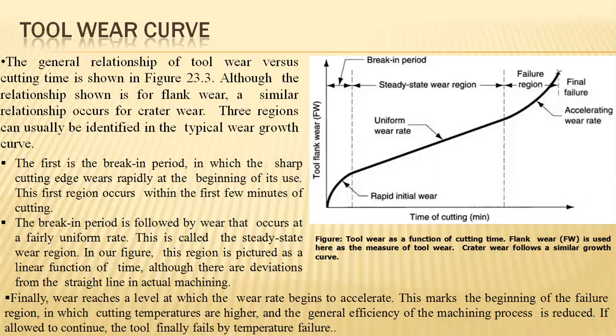Nominally, in the display, it is clearly specified that firstly the break-in period, where the sharp cutting edges are rapidly utilized in the machining process for a particular time period, and next the steady state period is entered because of the inducement of repeated loads over the work tool. So gradually the strains increase to a particular level, and if high frictional forces or thermal stresses are produced over it, directly the plasticity range, nothing but permanent failure of the tool, comes into the conditions.